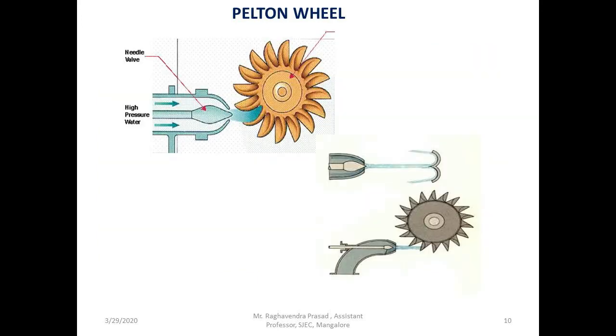Pelton cups are specially designed cups or blades. You can see in the diagram. This Pelton cup splits the water into two portions, and each portion of the water applies the same amount of force or pressure on the blade. Because of the special design of this Pelton cup, the loss of water during the flow can be reduced to a very minimum value.